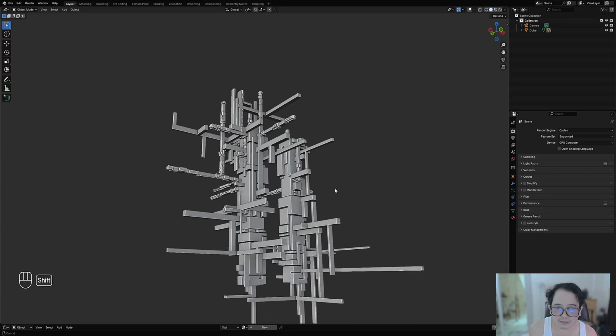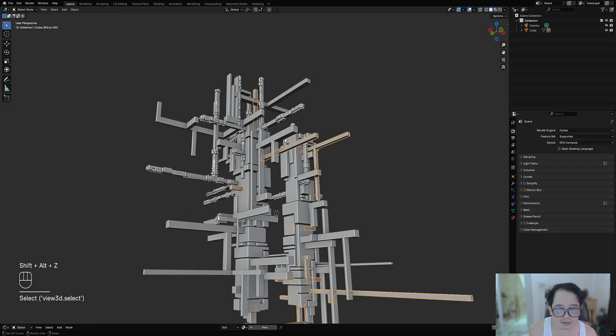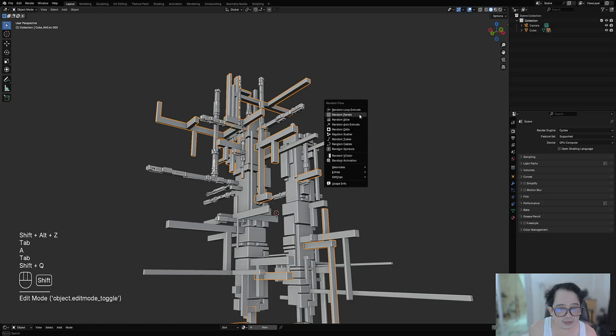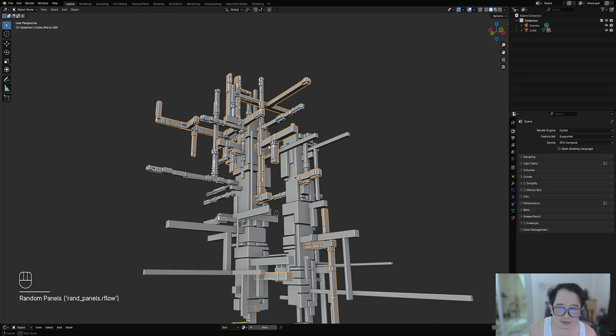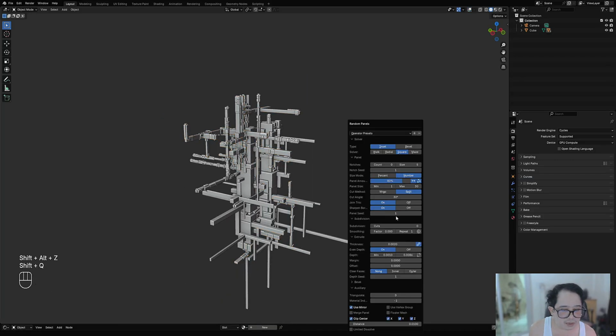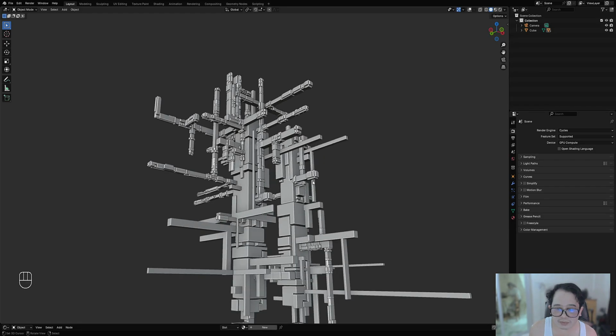Okay, and then try another random axis extrude result using the same preset. Probably just two layers per random axis extrude result, and the rest of the detail will be provided by the texture.